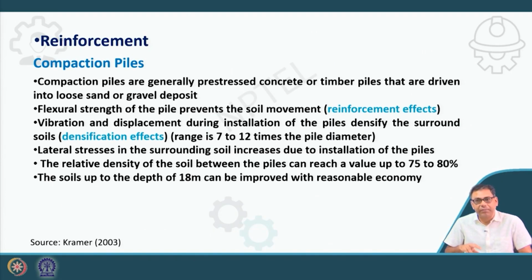So, it is a combination of densification effect and reinforcement effect, but the majority is the reinforcement effect. Okay. So, the range is 7 to 12 times the pile diameter. That means the soil surrounding the piles, in the range of 7 to 12 times the pile diameter, can be densified